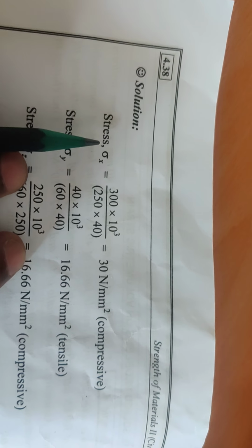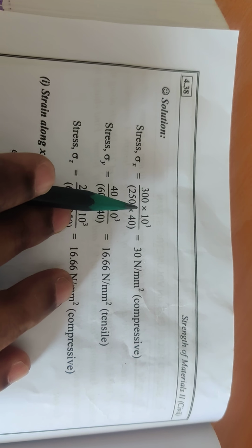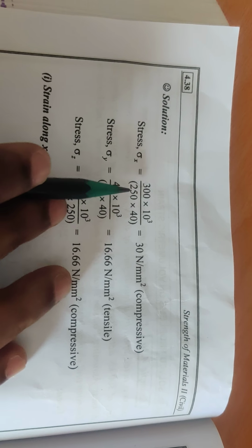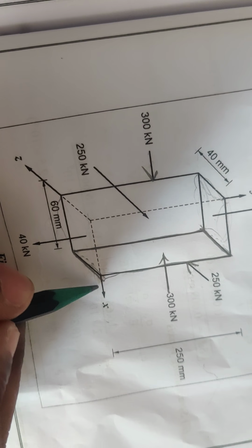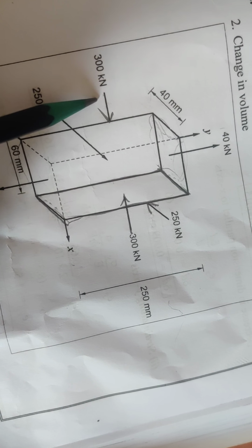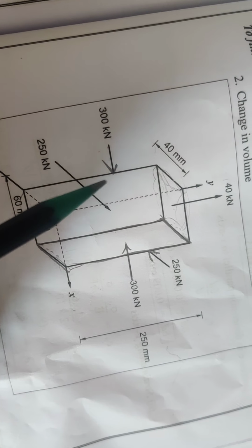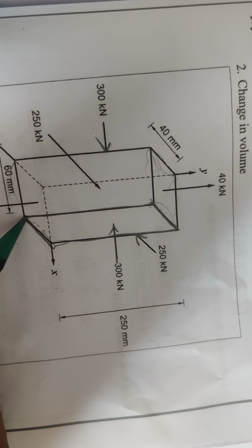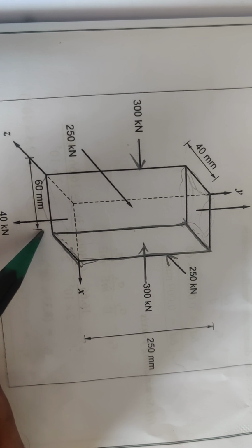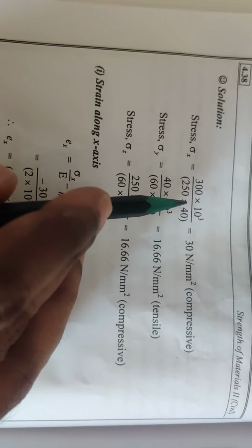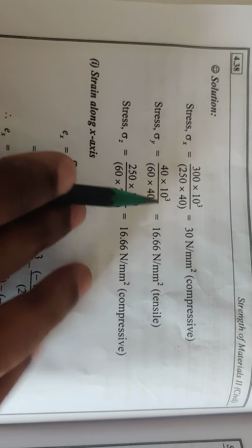So first we are calculating stresses. The first step is stress in x direction. Stress in x direction is equal to load in x direction divided by cross sectional area of x direction. This is the x direction, and in x direction 300 kilonewton is acting. The cross sectional area in x direction is the length and the width, so 250 into 40. We are converting 300 kilonewton into Newton: 300 into 10 power 3 Newton divided by area 250 into 40, we are getting a stress as 13 Newton